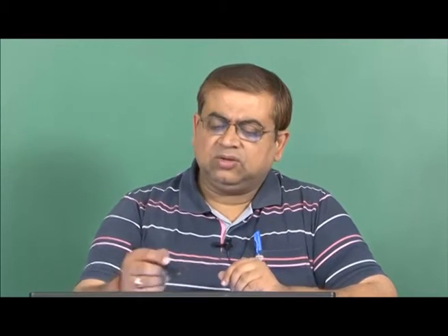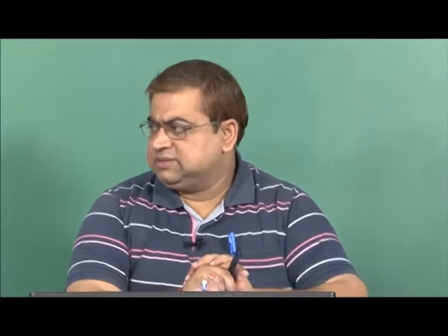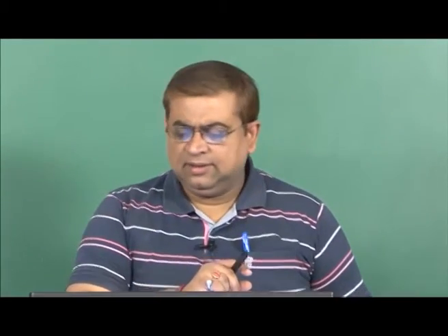So when we talk about optical lithography, largely we are basing ourselves on these resists, because these are what cause chemical transitions to happen, and these chemical transitions can be utilized in order to pattern surfaces through very small features, which would then be extended to the surface over which these patterns outlay. The extension can be in terms of either etching off the surface or depositing something on the surface, meaning thereby that we can do bulk and surface micromachining as we showed in the earlier lectures.